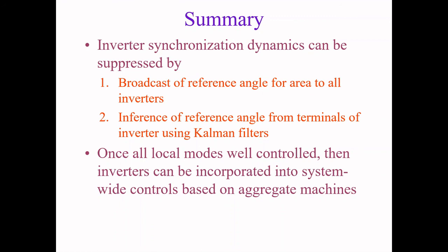Once we've got all those together, then inverters are just another component within the power system, and their operation is not radically different in its contribution to system dynamics. So if you're wanting better frequency management, if you're wanting better damping controls, then considering these large inverters as simple systems and controlling them based on your overall plan is the pathway to salvation, even with reduced inertia within the states.